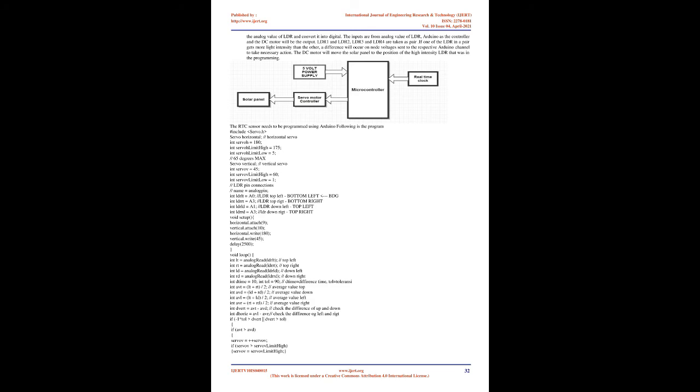B. Servo motor. Servo motor is a 3-wired DC motor which works on the principle of servo mechanism. Servo motor can rotate up to a maximum angle of 180 degrees. In our proposed project, a 4.8 V motor is used. Since it is a dual-axis system, 2 servo motors are used for east-west and north-south directions respectively. Servo motors are powered by PWM output received from the Arduino.